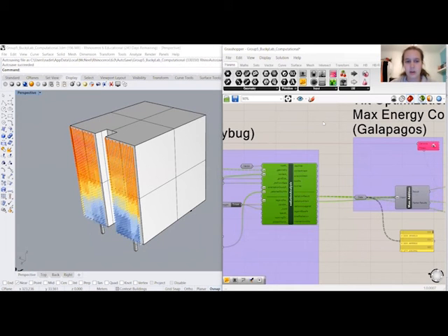We did take into account that the panels on top will shade parts of the panel on the bottom, which will reduce the radiation fallen on the panels on the bottom. Real PV panels, however, are affected more than just the part that is shaded because of PV stringing. Other parts of the panel, which are not shaded, might also be affected by the shade. This, however, is not being taken into account in our script, and it would be an opportunity to improve it.